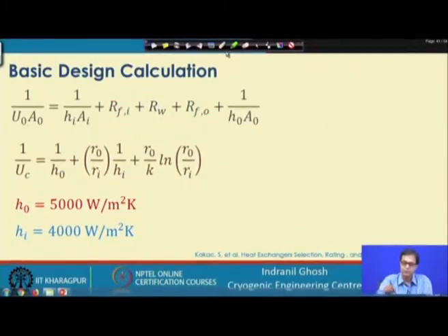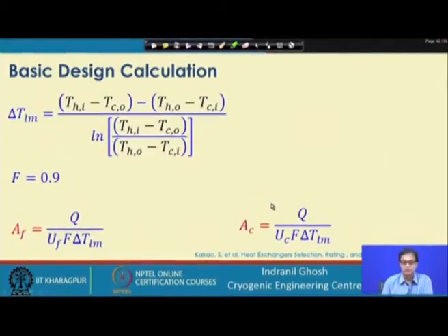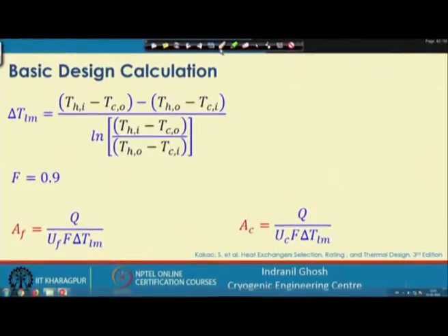So, now we will try to find out, based on this information, we already have the knowledge about the overall heat transfer coefficient, and then we have the knowledge about the heat transfer. Next, we have the knowledge of the overall temperature profile, or rather the exit and inlet temperatures. So, we will be able to find out the log mean temperature difference if the fluids are arranged in a counter current exchanger configuration.